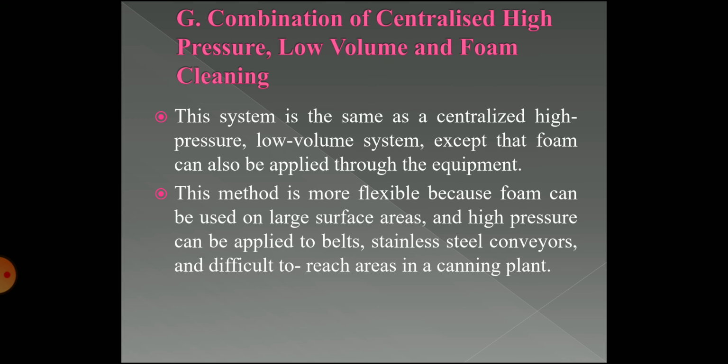Combination of centralized high pressure, low volume and foam cleaning. This method is more flexible because foam can be used on large surface areas and high pressure can be applied to belts, stainless steel conveyors and difficult to reach areas of the canning plant.